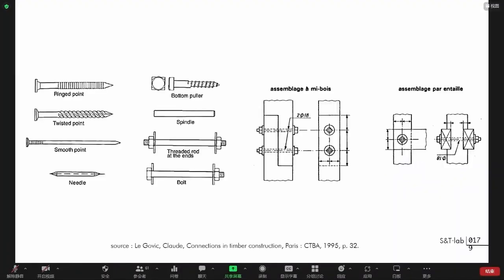Well, just a few words about timber joints. Timber joints are contact joints or use steel connectors. From this, you have different behavior against fire. As you know, you have to choose dowels instead of bolts that could be exposed to fire.